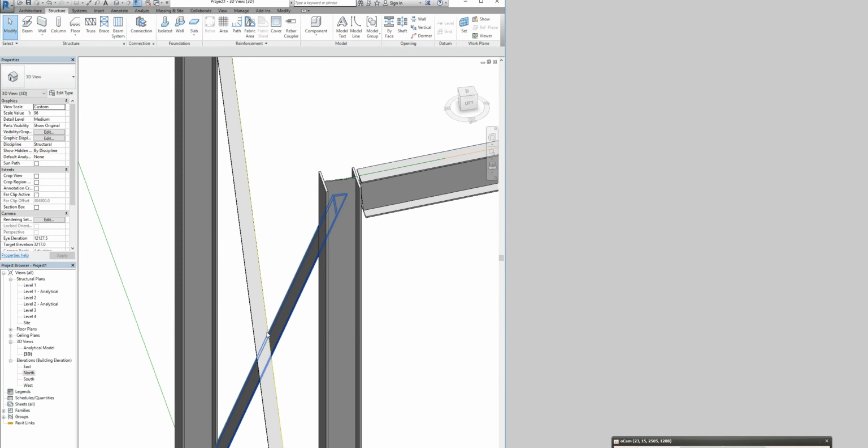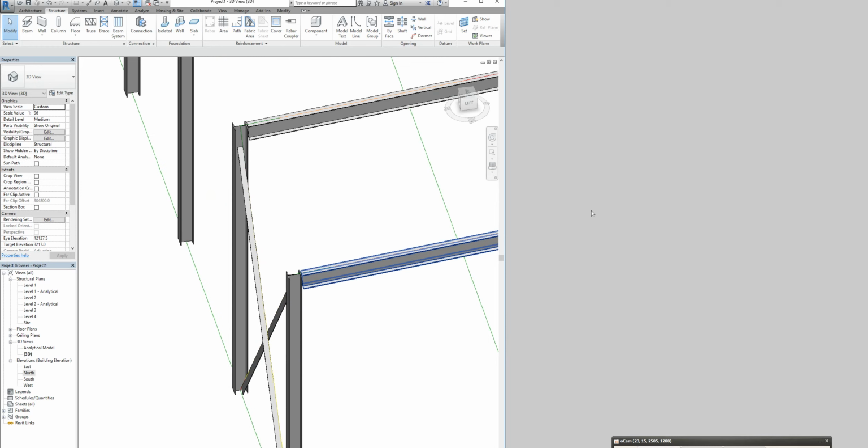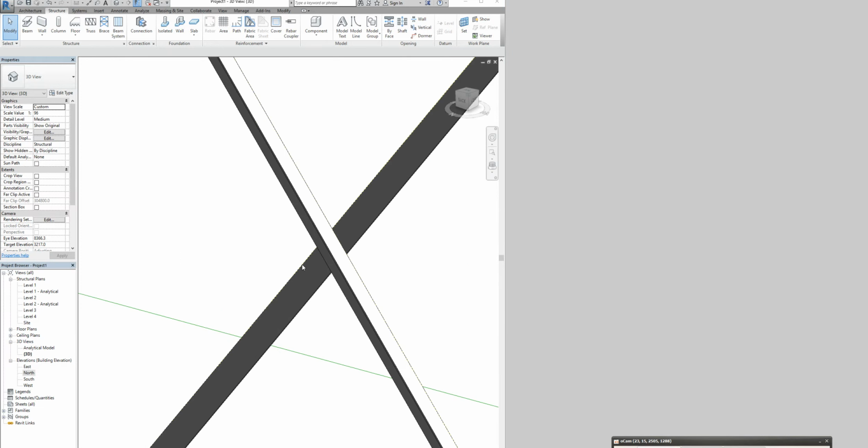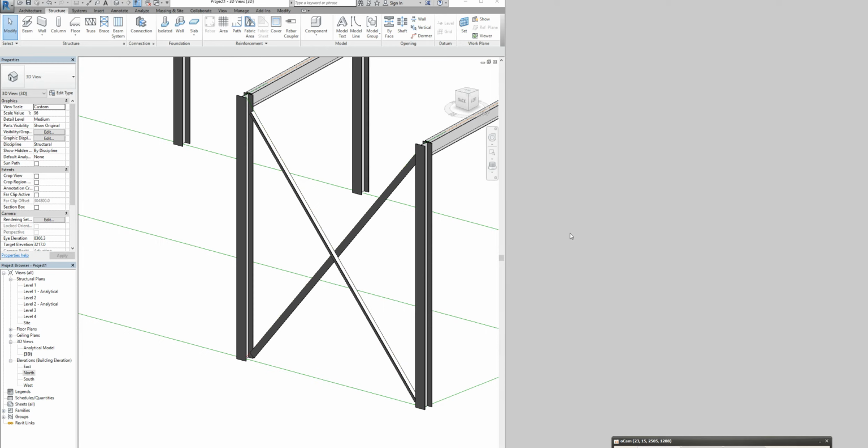It says only require rotating the brace using cross-section fill points, but these members, if we see from closer, they are facing back to back, so sometimes this might be 180 degrees rotated to the other side, so that's not a good joint, so that's when we have to rotate. But in this case we don't have to, so it should be fine.